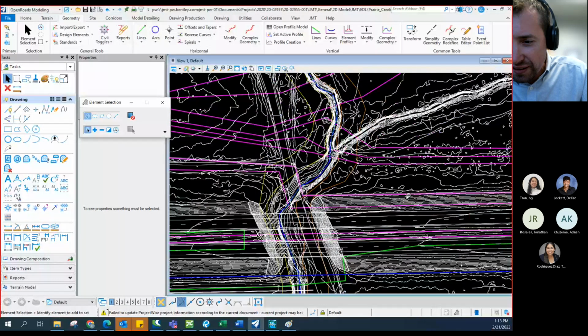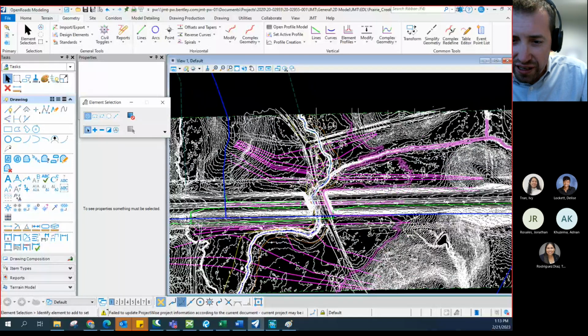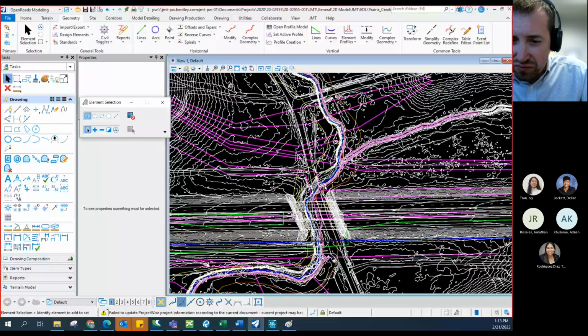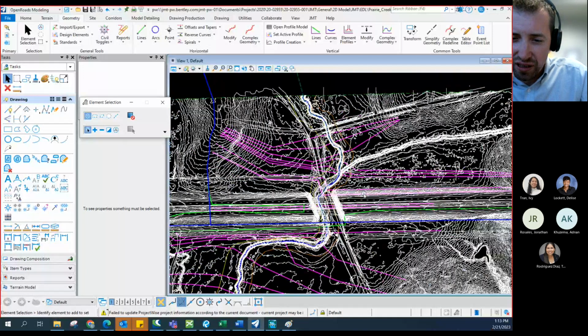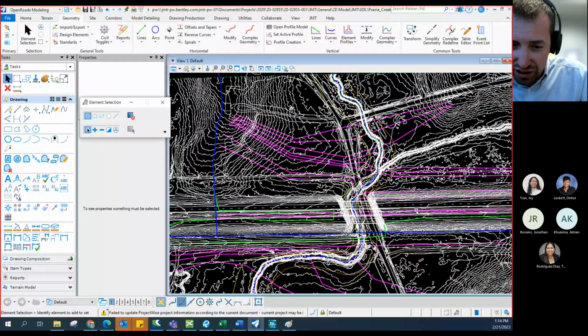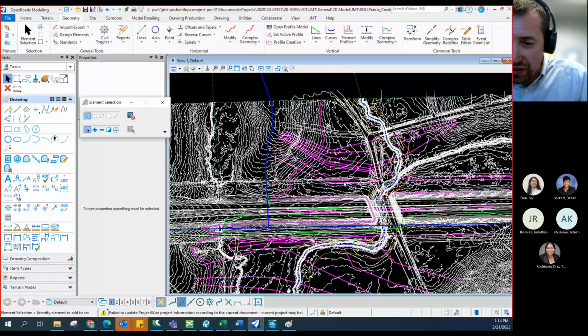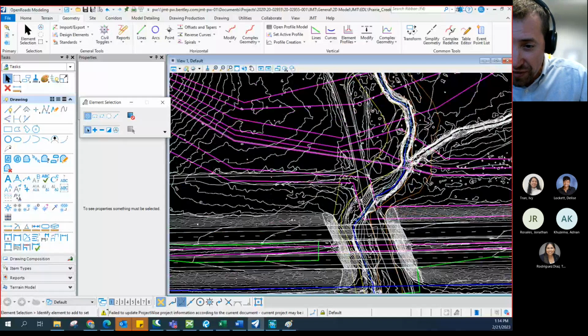So I started it at the end of the section and then drew it there, then across the channel and then back up to the floodplain on the other side. That happens a lot when you have roadways. The roadway usually creates a berm, so your cross sections on the downstream side start to run parallel to the roadway. So I drew one there. That's close enough to being the fully expanded flow on the upstream side.